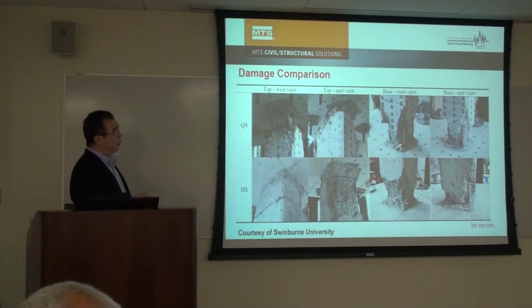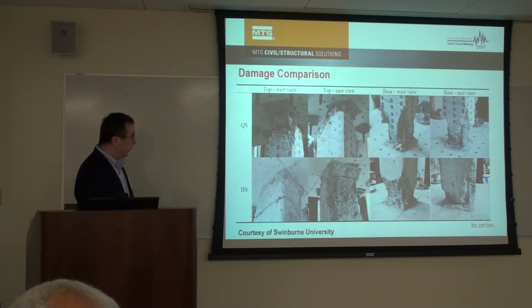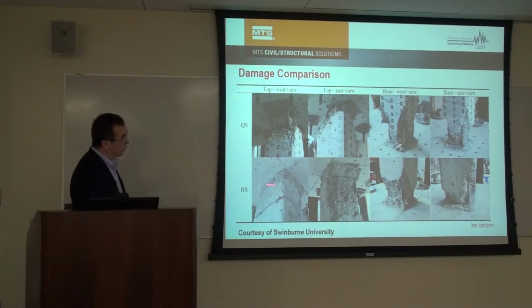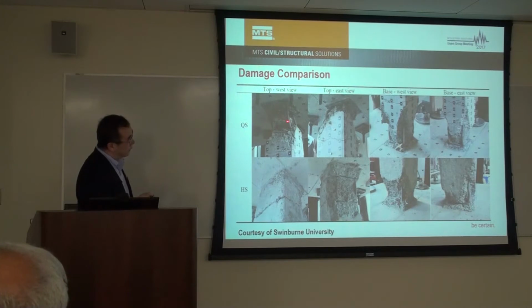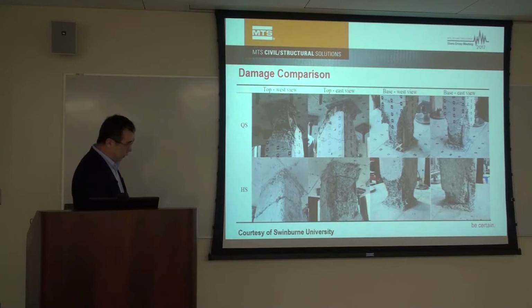They also did a regular quasi-static test according to some predefined specification. This is the quasi-static test, and this is the hybrid test. The hybrid test is simulating one specific earthquake, and the quasi-static test is just rectangular loading, and you can see the damage. The quasi-static test has a lot more damage than the hybrid test.